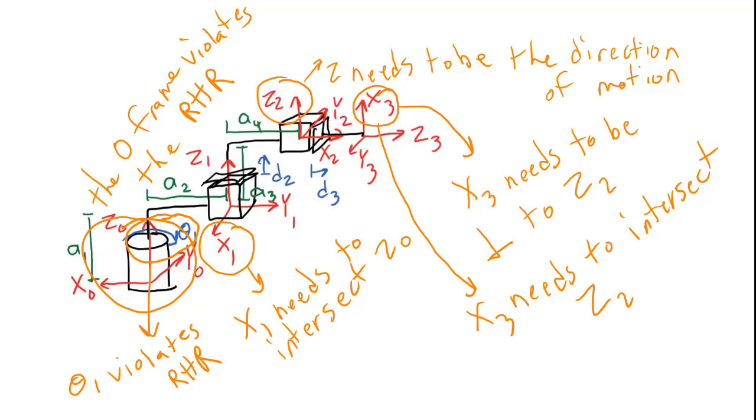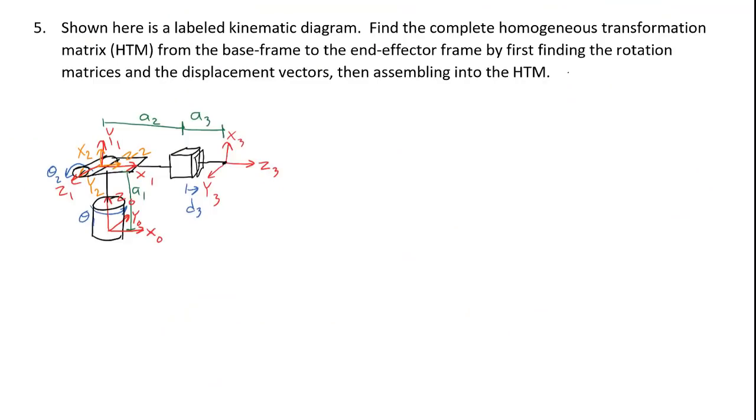If we check the link lengths, we'll see that one of the link lengths is not labeled. So right here in this distance here, this needs to be labeled. Link length, not labeled. And I think that's all the errors you could find in this diagram.